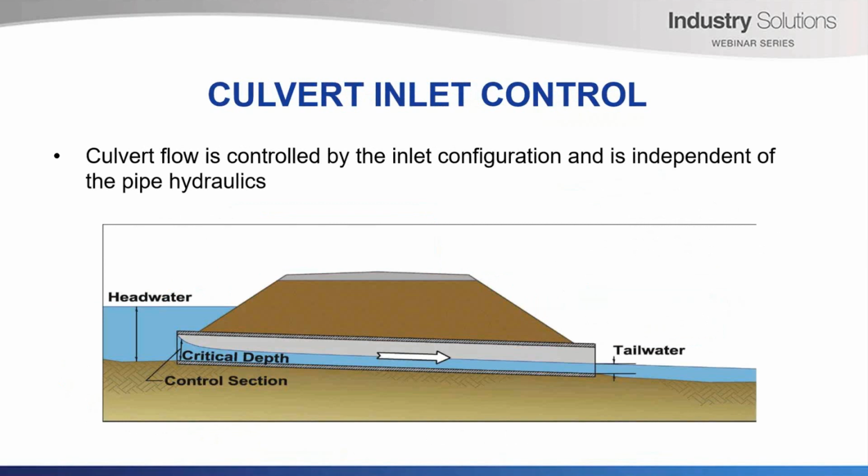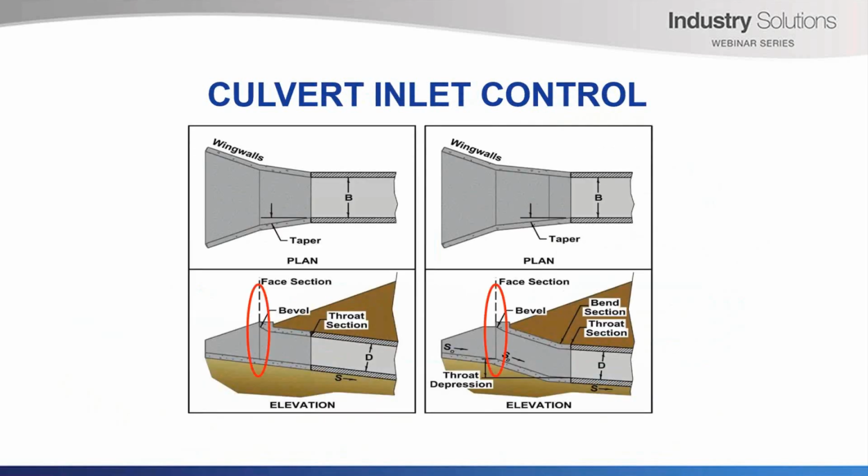So the second part of culvert design is inlet control, and it's not particularly well defined. The concept is fine. Flow is generally supercritical, and the culvert characteristics don't play any role in the calculations. It's only influenced by the headwater and the inlet configuration, but quantifying it's another matter. So we know there are three main components.